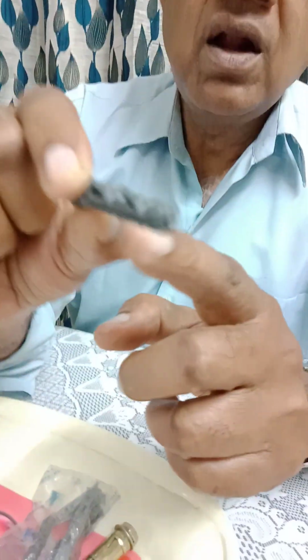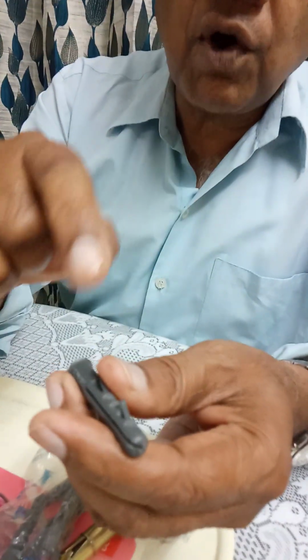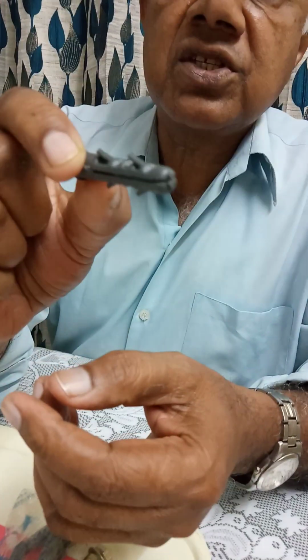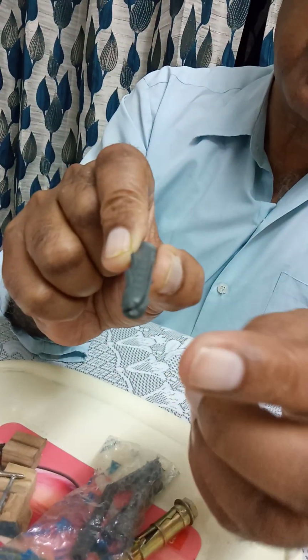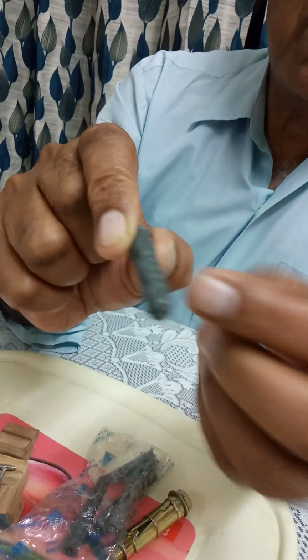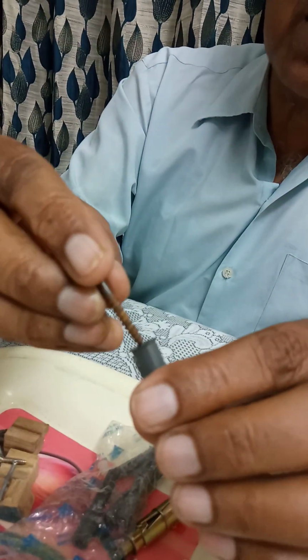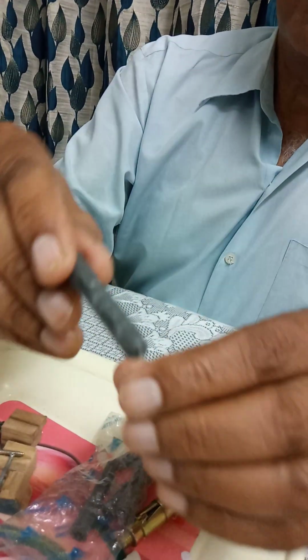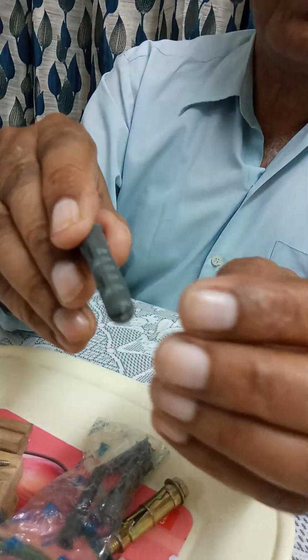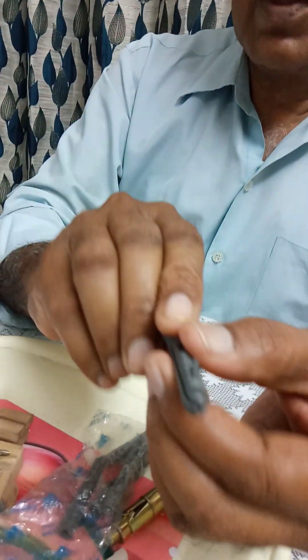This is a typical nylon sleeve. This device is called a sleeve. So we create a cavity in the wall and then we push this sleeve inside, and you see these arms, they are in the opposite direction and they hold. As soon as we drive this screw inside this sleeve, they hold the screw very tightly.